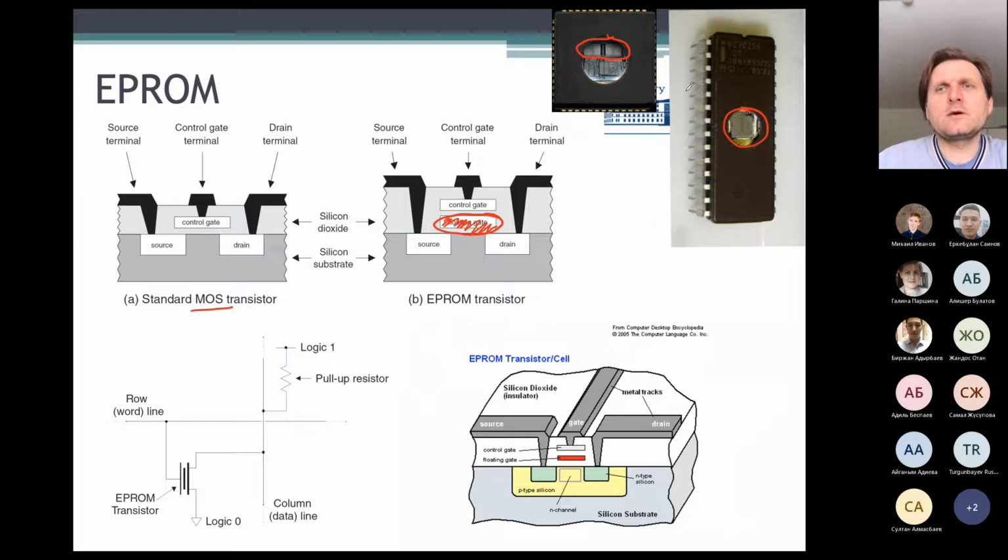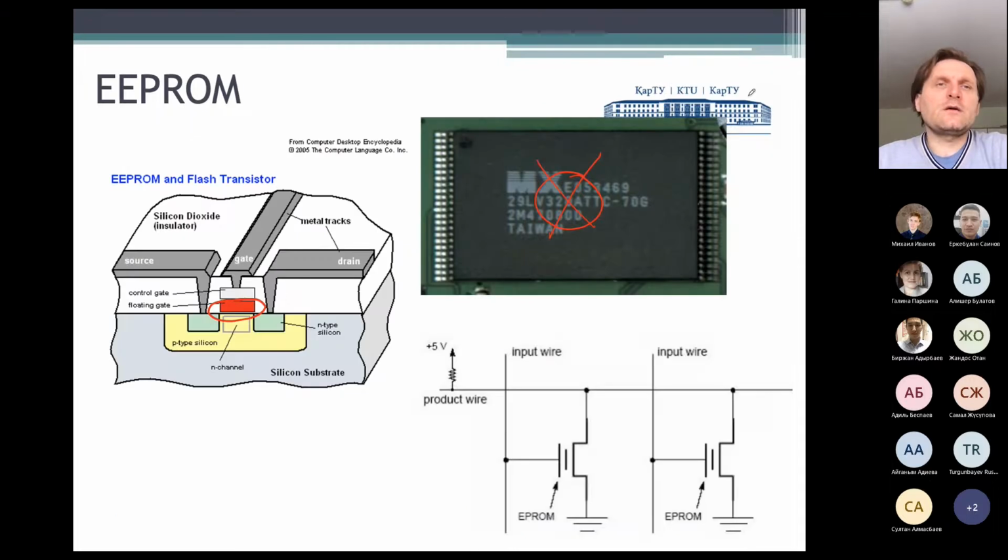But in that system, we should remove the EPROM from the PC board, put it into the programmer, and next go back to our system. With EEPROM type of memory, programming is possible when the memory is soldered into the system.